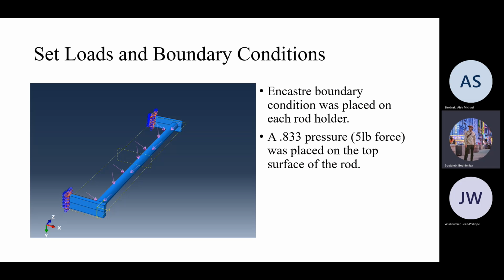As for our set loads and boundary conditions, an encastre boundary condition was placed on each rod holder. A 0.833 psi pressure, which is a 5-pound force, was placed on the top surface of the rod.